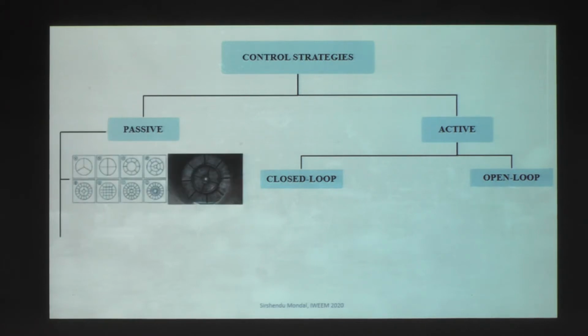Passive control essentially involves design changes, such as the use of baffles, resonators, dampers, etc. They target either reducing the total acoustic efflux or acoustic loss, or disrupting the phase relation between pressure and heat release rate oscillation, so that there is no thermoacoustic instability.